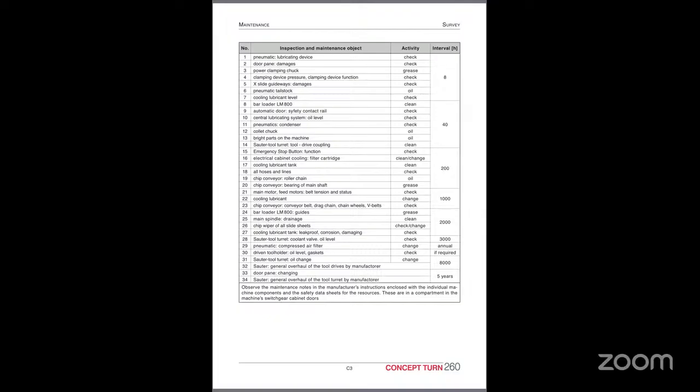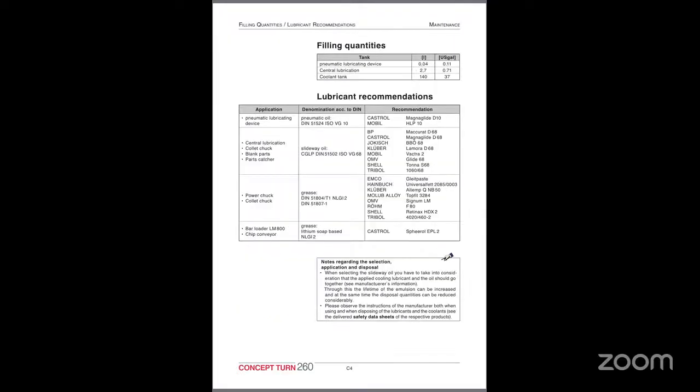Here in this machine, we have lubrication oil and coolant. So you should maintain the level correctly. What is the level of the lubrication oil, as well as what is the level of the coolant? Use the recommended lubricant only. The lubricant is used in ball screws, guideways, and slides.